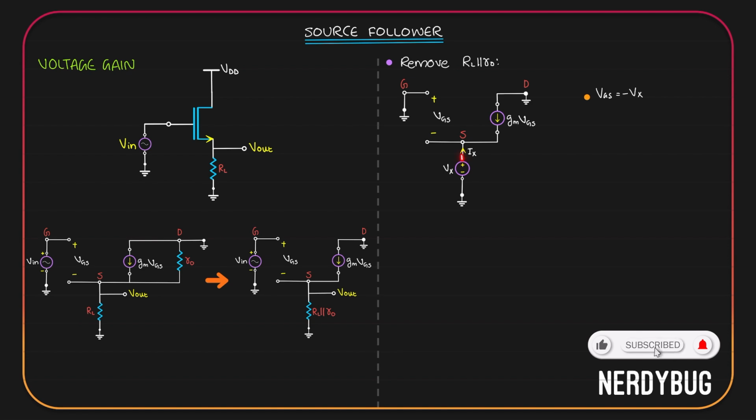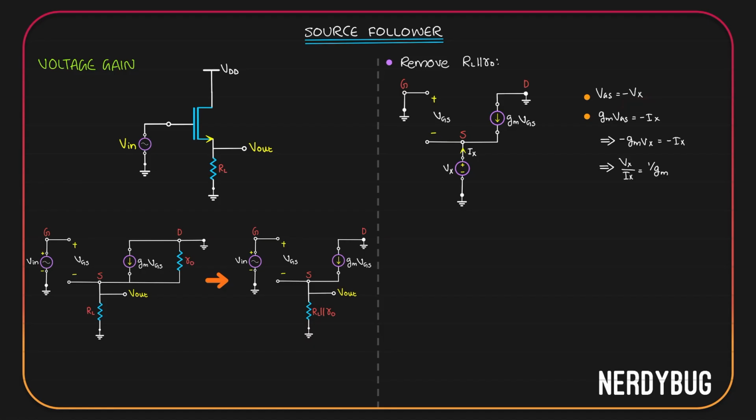Also, we can see Ix is the current flowing like this, GmVgs is the current flowing like this, which means they are equal and opposite. GmVgs is negative of Ix, but Vgs is negative of Vx. So we get Vx/Ix is 1/Gm. This much of the circuit is equivalent to a resistance of 1/Gm. Using this idea, we can simplify this circuit model further like this.